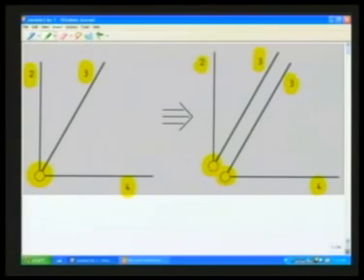This way, I can think of another type of hinge where 4 links are connected, and such a hinge will obviously be equivalent to 3 simple hinges. Maintaining this equivalence between higher order hinges and simple hinges, we would like to modify the equation for calculating the degrees of freedom of a mechanism as follows. When higher order hinges are present, the symbol j in the equation I would like to modify as follows.